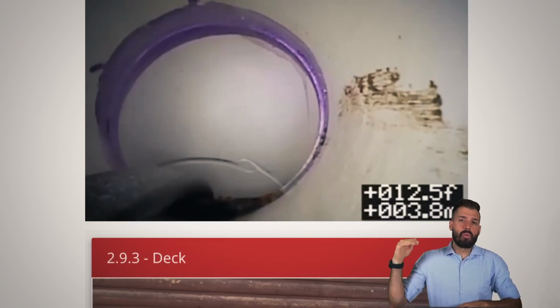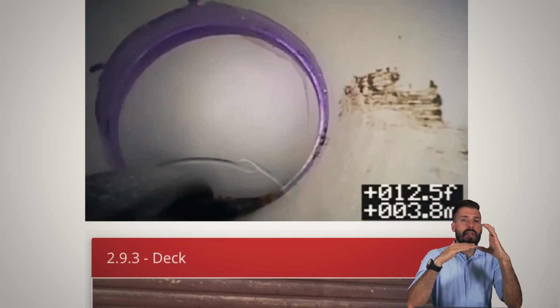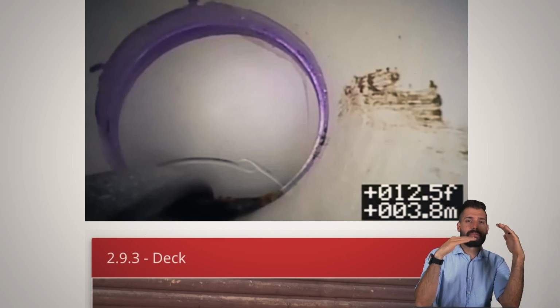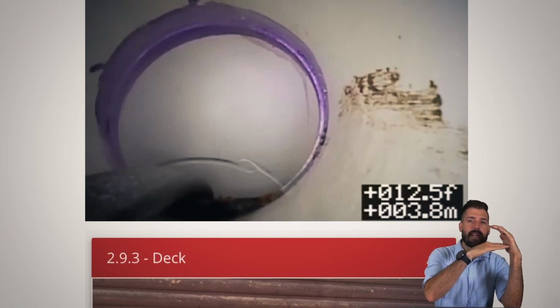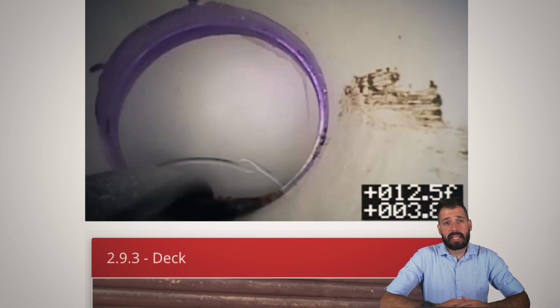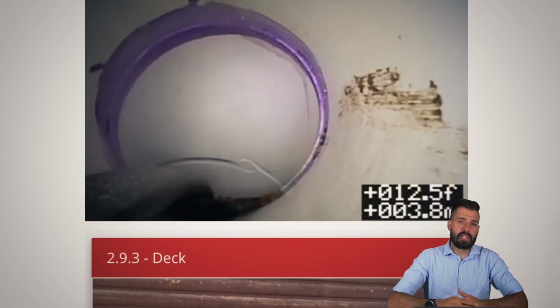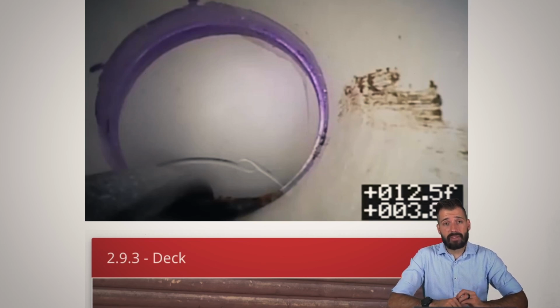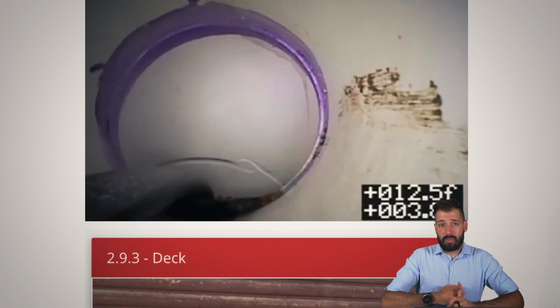And right at this one elbow, we have this crack in this joint. So the water was rushing down, and right where this 90-degree bend is, the water was hitting right into this crack, and then following the pipe the rest of the way down, and flooding that downstairs bathroom. Because that's where the gutter comes out to the exterior, because it's an interior gutter. But because of that crack, instead of having to do tens of thousands of dollars of repair, they knew exactly where the crack was, and they can do a very localized repair.